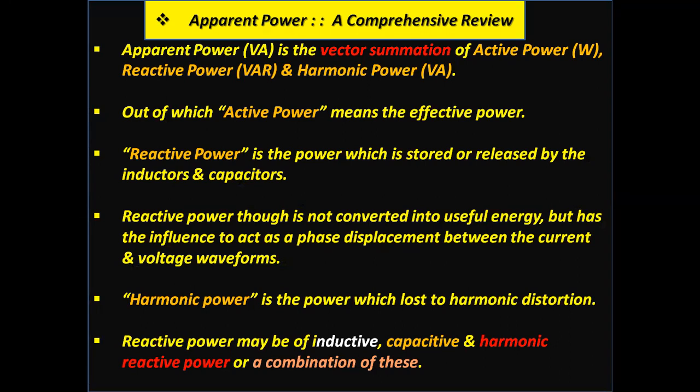Reactive power is the power which is stored or released by the inductors and capacitors. The reactive power, though, is not converted into useful energy, but has the influence to act as a phase displacement between the current and voltage waveforms.